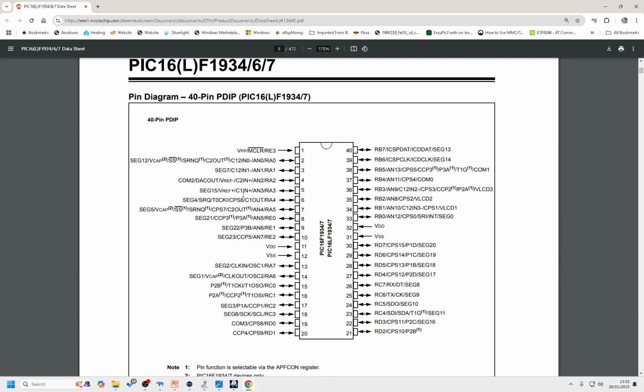We're looking in this massive stuff for CCP1. And it's here on RC2. And this one is movable, look. You can change CCP2, sorry, to an alternative, and I think you can change it to RB3 up the top here. So you can move things around, but very limited.